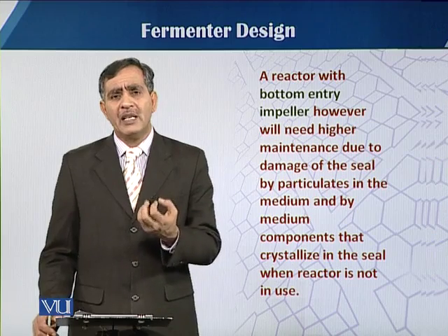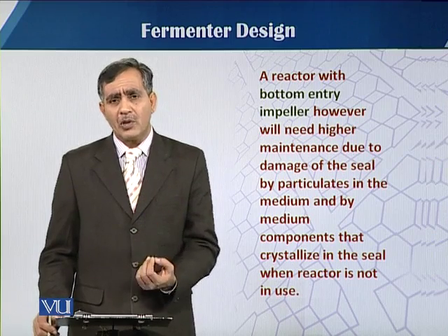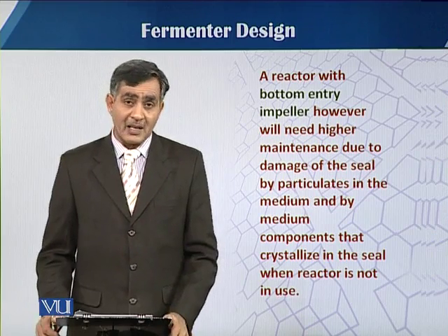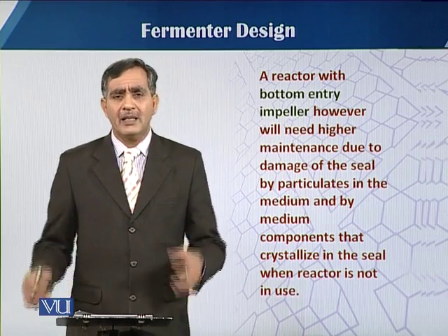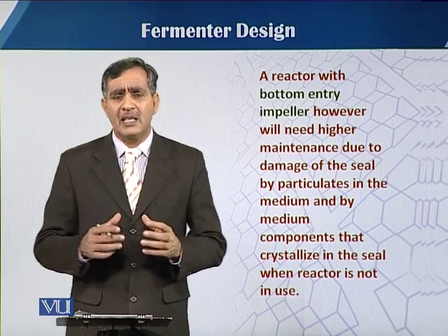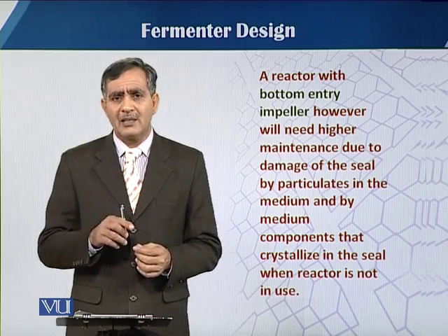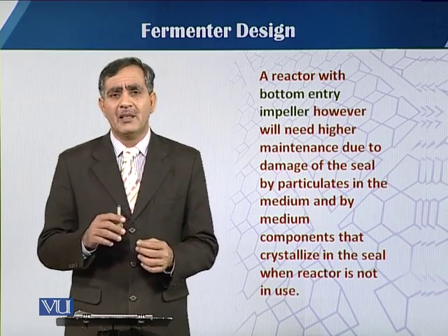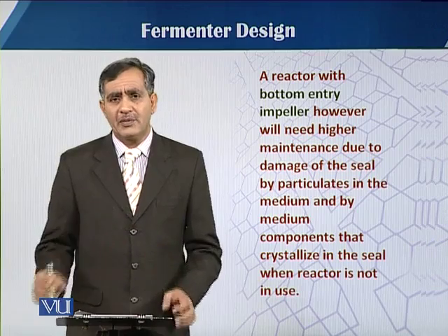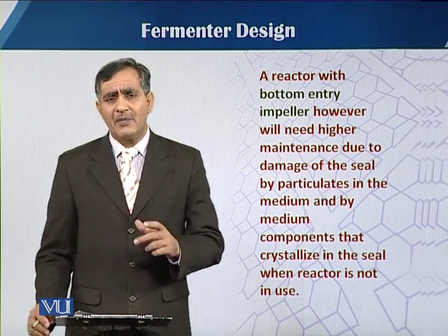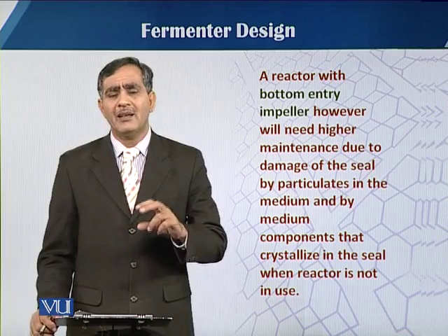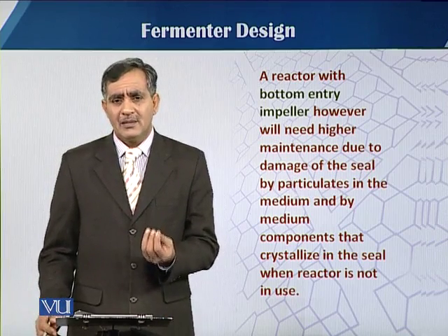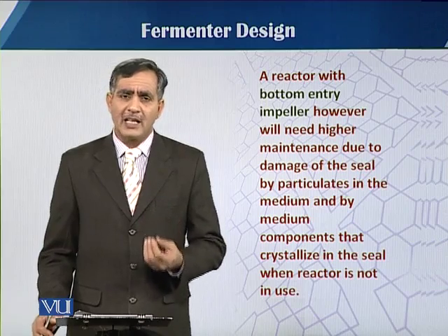But when we fix the motor on the bottom and the shaft enters from the bottom, there is also a limitation, because in the medium there is a precipitation of crystals, and those crystals cause some mechanical disturbance with the shaft and with the seal, and then the life of the seal is very short. So there is a limitation when we have the motor attached to the bottom.